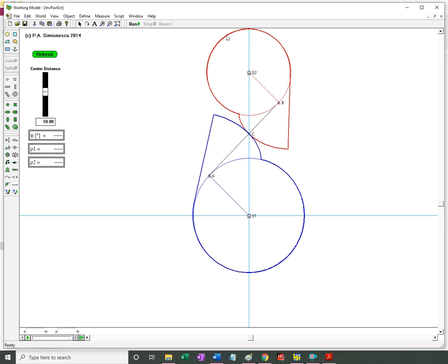The cross belt or the ribbon gets wrapped around this cylinder, breaks contact, and now it's wrapped around the other cylinder the opposite way, and I have a pencil here. If I hit run and record the locus of this point with respect to one or the other of the discs, I'm going to generate the flanks of the two teeth in contact.